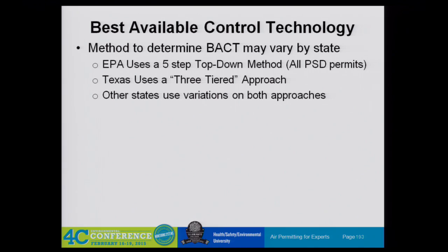Quizzing the actual source, like, these guys put in biofiltration for this VOC source, and does it work? Well, it works about 40% of the time if the loading levels don't get too high. So you find out all the qualifiers that you can use in your analysis to see if they're appropriate or not, even though the BACT may not mention all those qualifiers that in real life are really important.